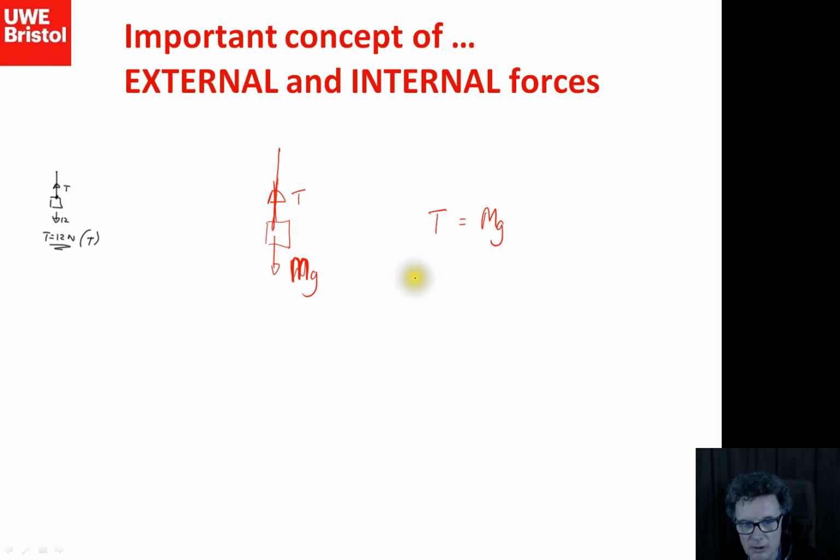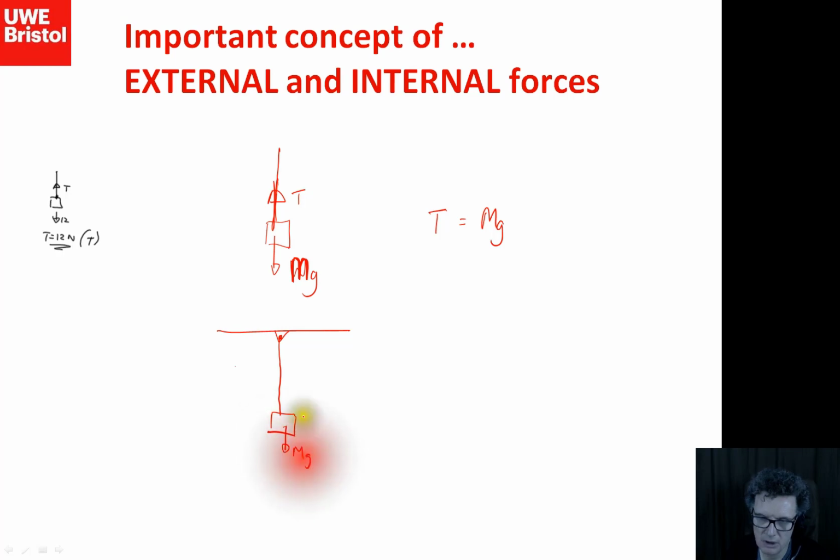We have just done the first example of method of joints, because this problem that was given at school is not strictly makes sense, really. What you're actually solving is we've got a piece of string attached to the ceiling. We've got the weight coming down here, mg, and then we've got a reaction force here at the hinge. I'll call that R hinge. That's the problem we're actually solving.